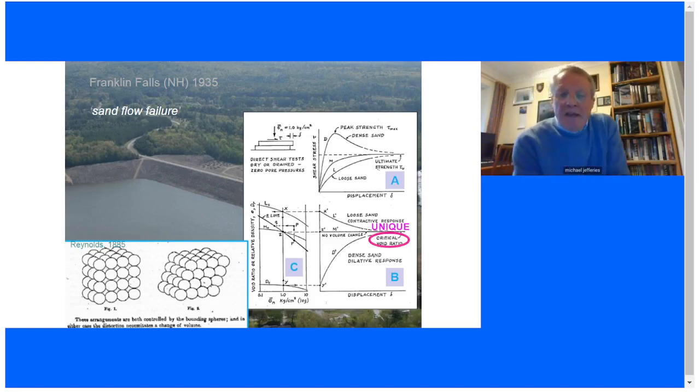Anyway, what we have here is a shear box, which is the top left sketch, and they've done a series of shear box tests. And what they observe, and it's marked in as plot A, is that if you have a dense sand and we shear it, as you all know, it dilates and we get a nice peak strength. If we shear a loose sand, we don't get a peak, it just gently increases in strength as we displace it sideways. And what they found in their testing was that whether it was dense or loose, it went to the same ultimate strength. So far, so standard.